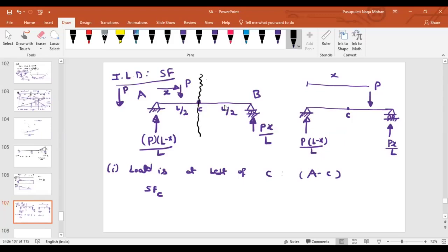If you look into the right side, how many forces are there? One. If you look into the left, two forces. So the shear force is the algebraic sum of forces either to the left or right of a section. In this case, which one will you prefer? Will you look into the right side or the left side? You guys are very smart people.